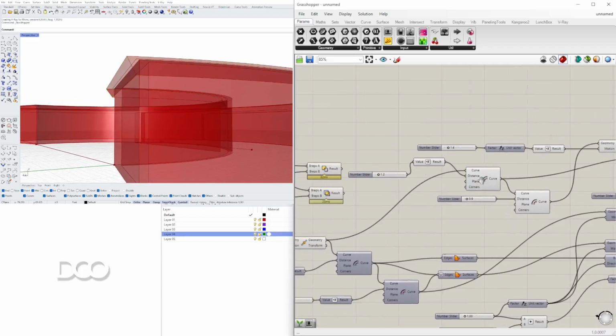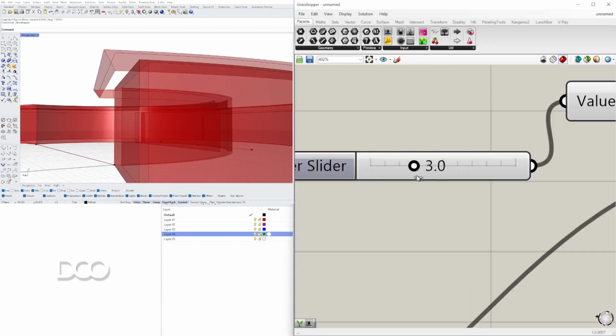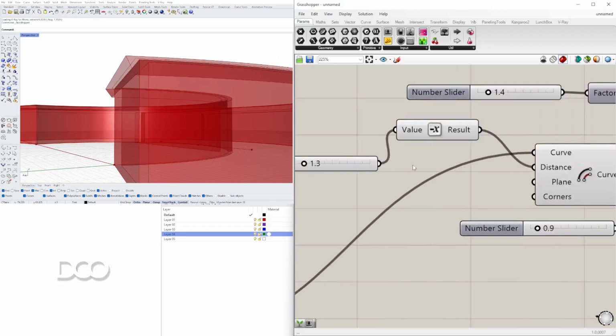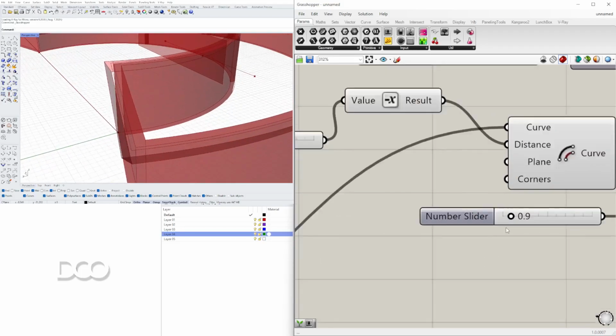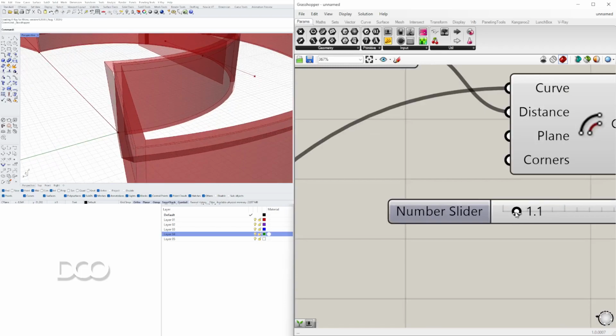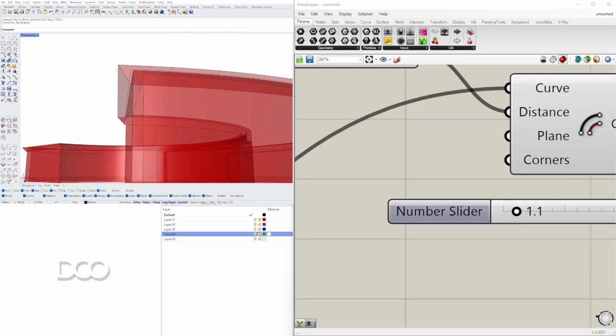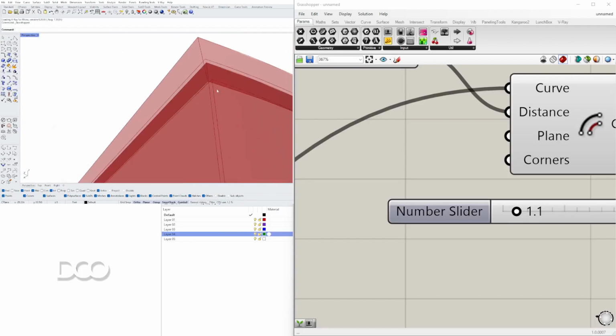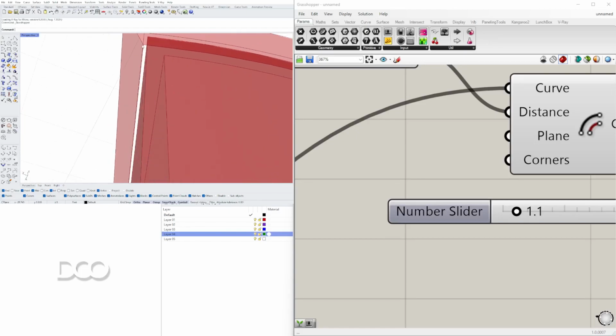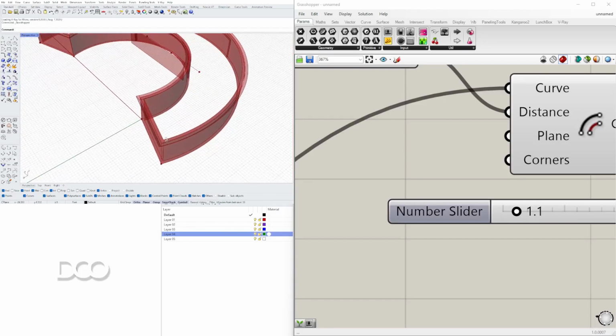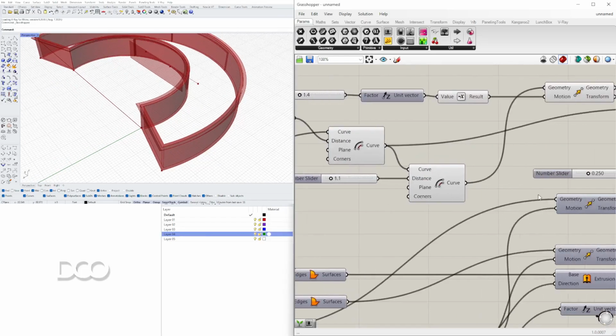So this is why we offset it to the outside to create an overhang, and we offset it back to the inside to make sure that we have a slope. But the reason why we want to keep a little bit more than the wall is because we're going to subtract it from a form.